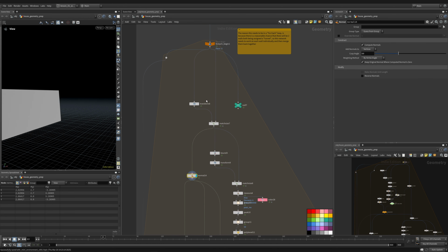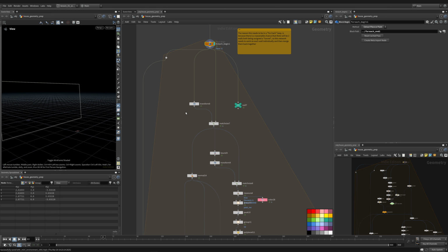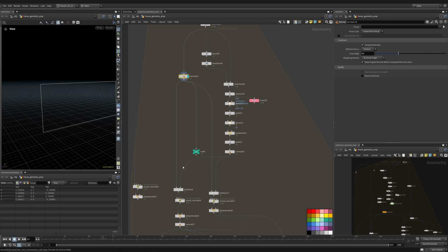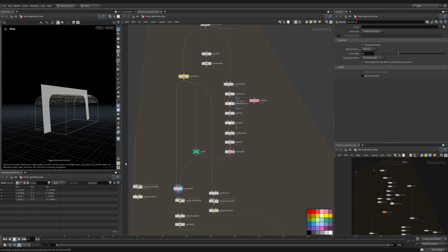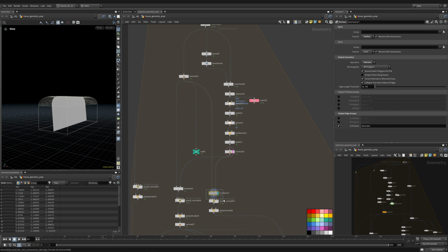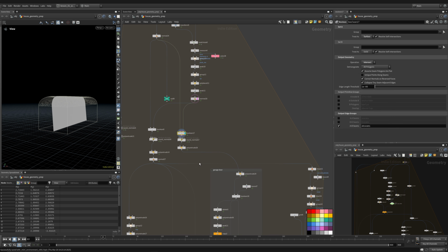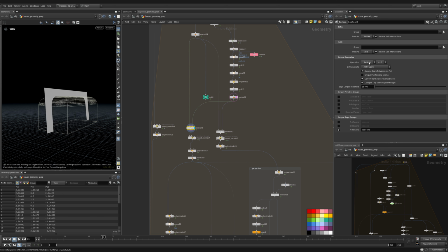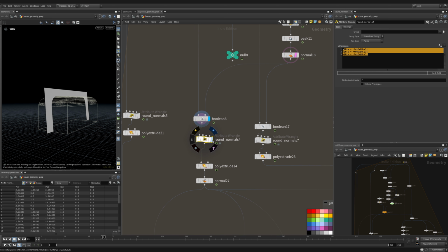So we get our incoming geometry, which we shrunk down a little bit. And then we Boolean that with this side here, which we've created. And now what we want to do is we want to extend the garage. And notice how in this Boolean, we kept the inside because we were making this garage door. What we want to actually do is we want to keep the opposite. So we're going to do subtract rather than intersect. We're going to round the normals. There's also a few ways to do this, but this is the way I chose to do it.